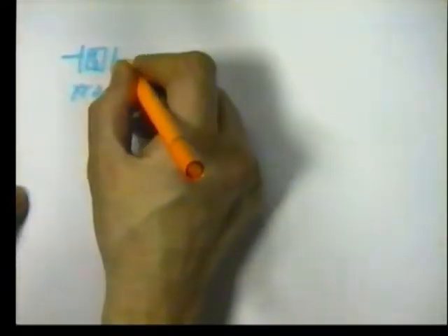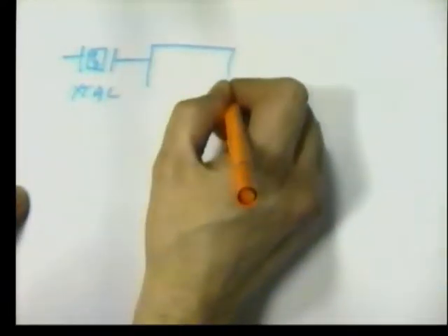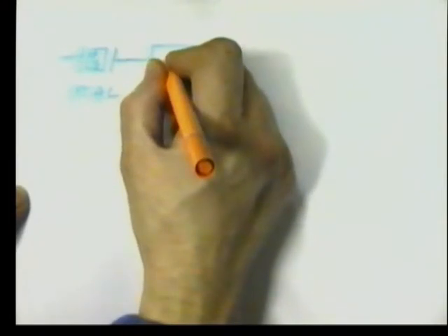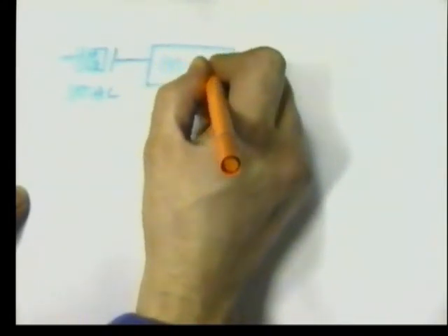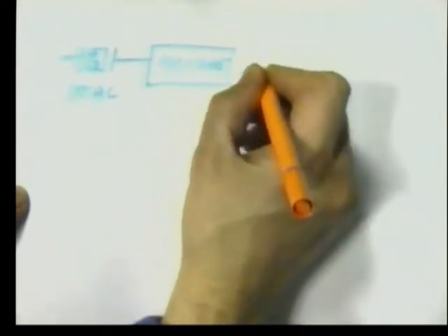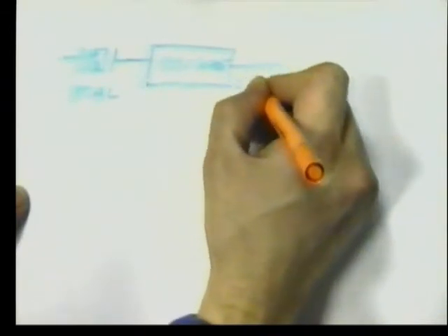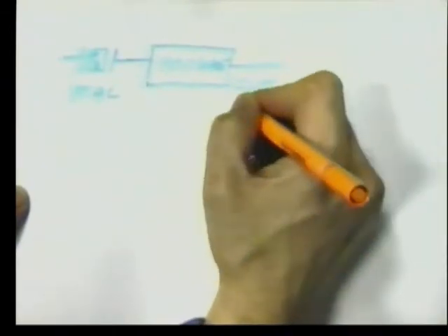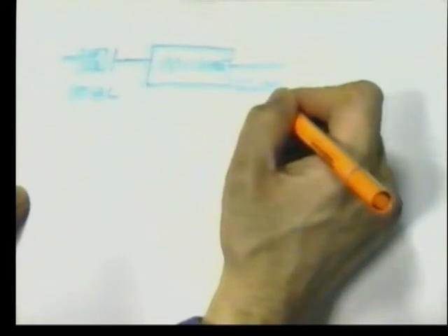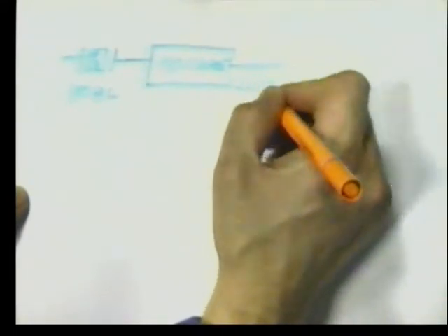Now that usually is far too fast for us to use in processing. So internally, there is always some fixed prescaler that divides it down to something more usable, and that is usually referred to as the system clock or the machine clock or the internal clock. That is the timing reference we're interested in.